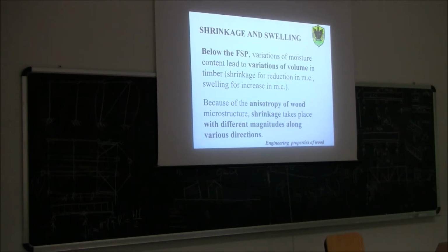Instead, if we put the wood on the building site, in our structure, without drying it, then we allow this moisture content variation to occur later. So basically, we don't dry the wood. Then later on, we will have different conditions. Since the wood is also tied to the different parts, those restraints are additional and make it easier to get distortion and some crack formation. That's why we need to dry the wood before it is used in structural applications.